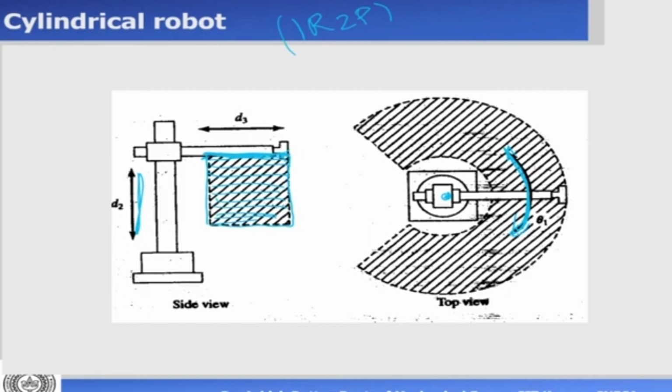Okay, and it's a plane. It's a square or rectangle depending on the dimensions of D3 and D2. If they are equal, it's a square, otherwise it's a rectangle. Now, when we are seeing this planar figure from the top, the edge view will